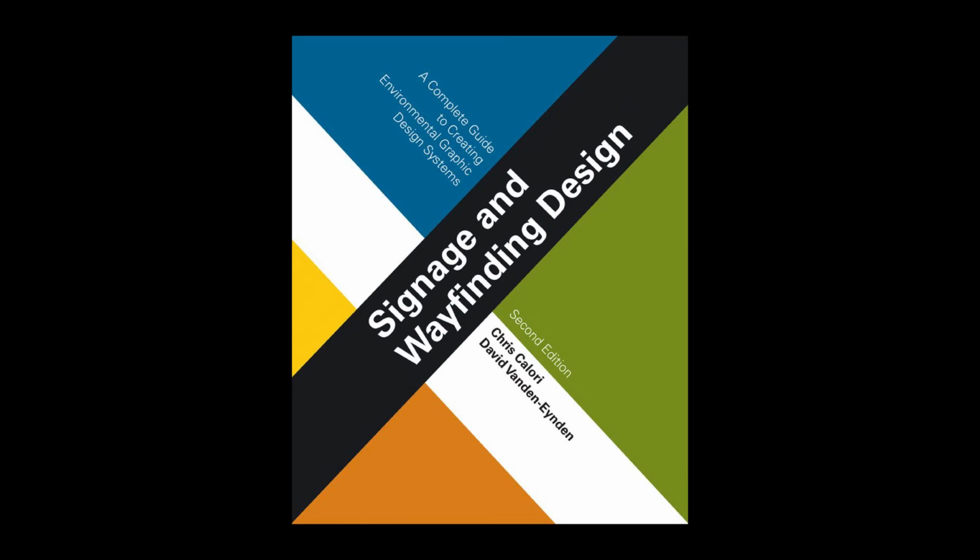Plastics and plastic resins are also moldable by various processes into an infinite variety of shapes, an invaluable feature in signage design and production. Plastic in sheet form is most commonly used in signage, although plastic resin liquids and pellets can also be cast into various sculptural forms. See Figure 6.40. The two primary sign plastics are acrylic and polycarbonate, commonly called polycarb, both of which have the